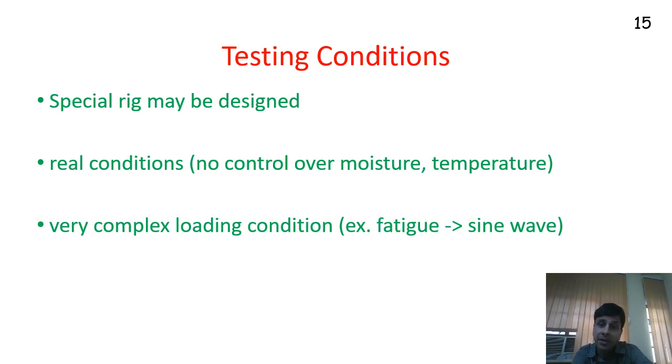And it can be a very complex loading condition where you actually collect data from a real application and you subject the part to that data. So the testing condition is that you might have to design a special rig, as I said a few minutes ago. And the problem is the very complex loading conditions.